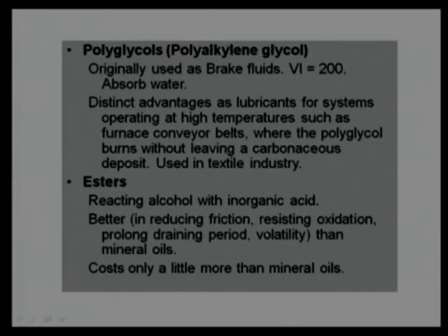They show lesser friction and lesser oxidation, more resistance to oxidation, and because of that good resistance to oxidation, their draining period is large. Obviously, they do not require frequent replacement.